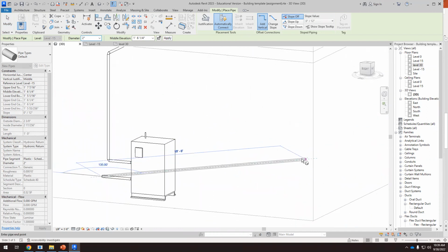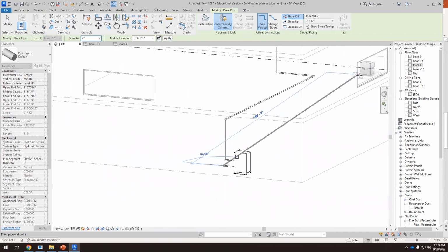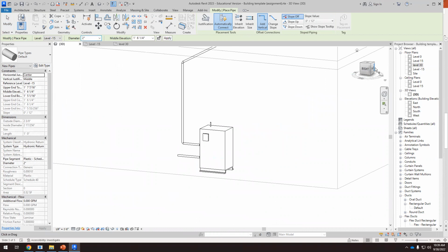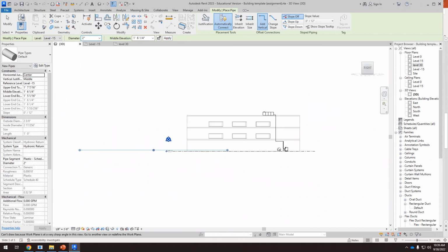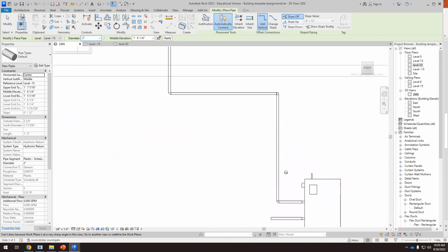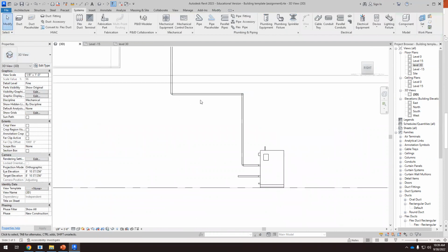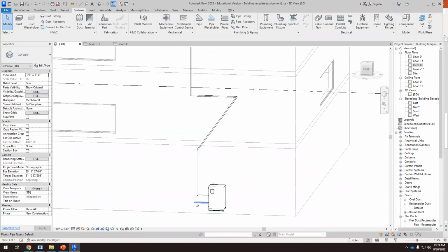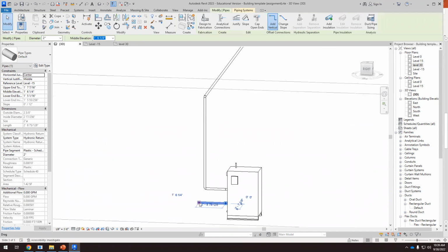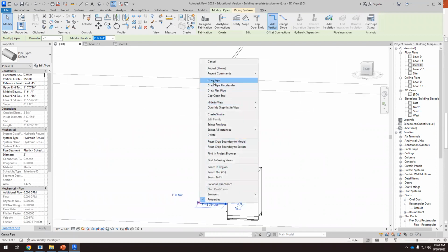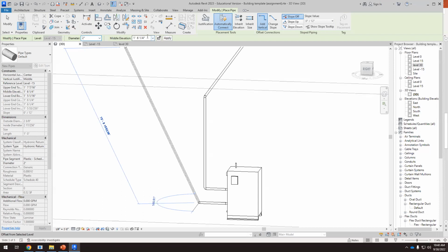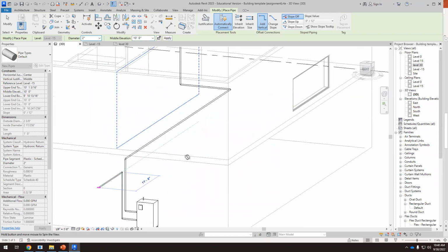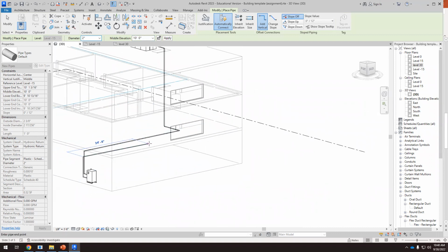And now we have to go up and make sure that you rotate the views so that we don't have any intersections here. So now from this one, I can go up, draw pipe by changing the elevation to 10, and then I want to go horizontally.